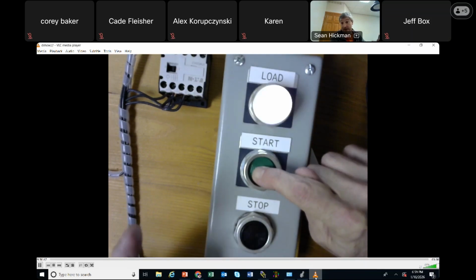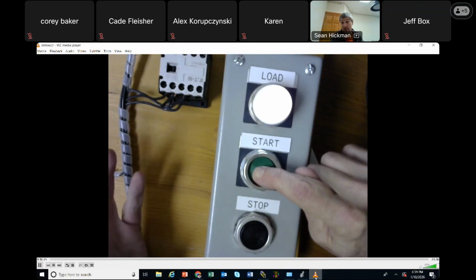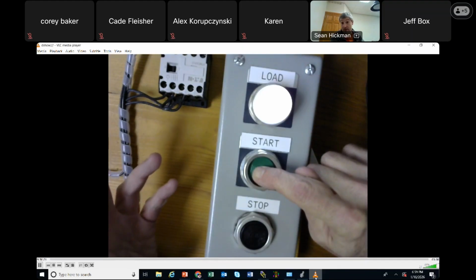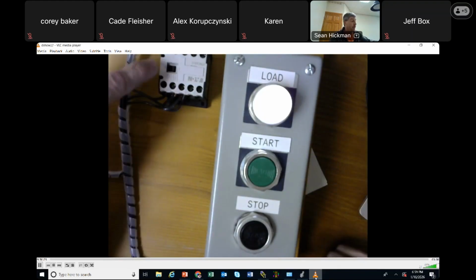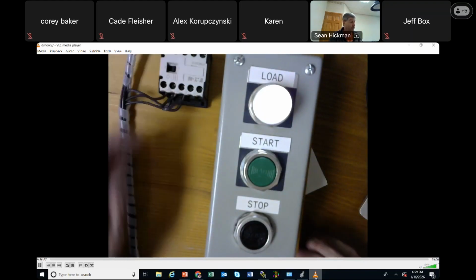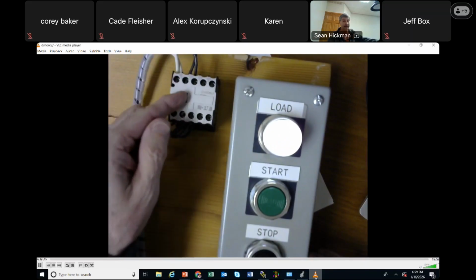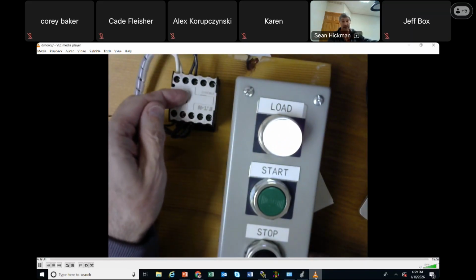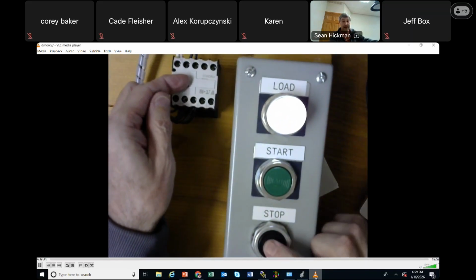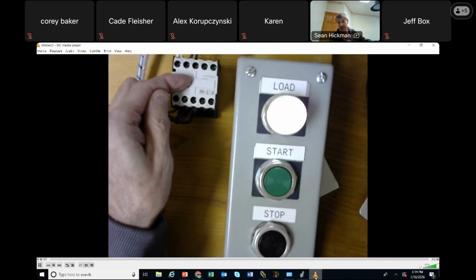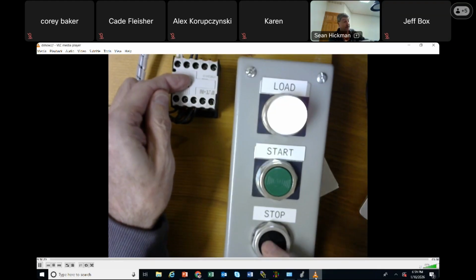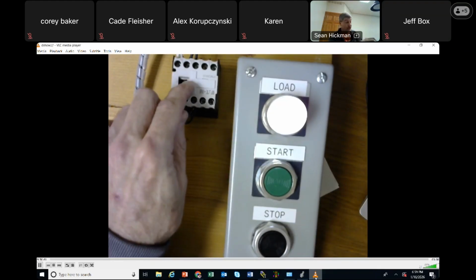But as soon as I let go of the stop again, Johnny would continue getting ground up. Or if I hit start, and for some reason one of the contacts in the holding relay or some of these other contacts get fused on, I hold this indicating that it's on, and I hit stop, whoo, Johnny's safe. But as soon as I let go of this, it comes right back on because the contacts are fused on.